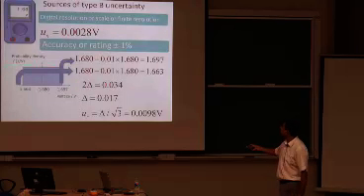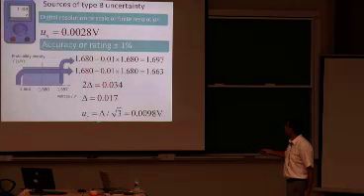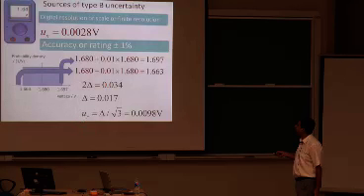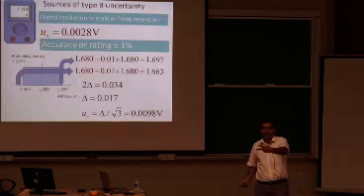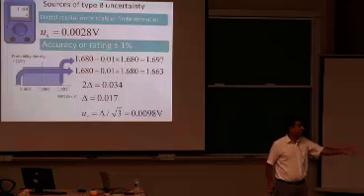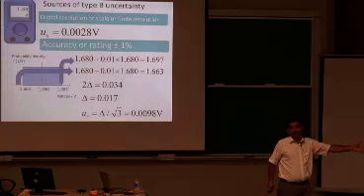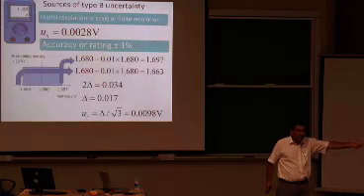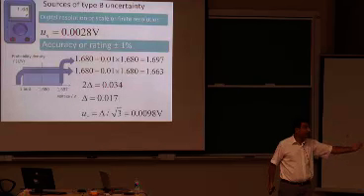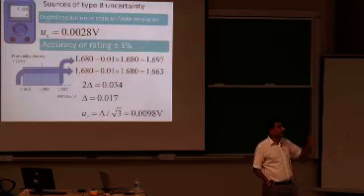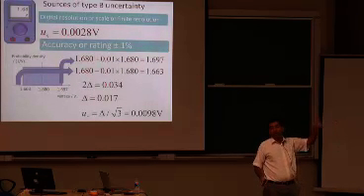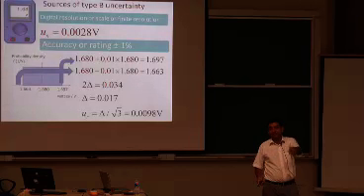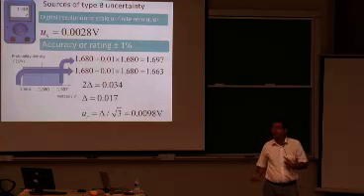So now I have 2 delta, I find out what delta is, and then I again divide by root 3 to find out the uncertainty due to rating. So I have 2 sources of uncertainty here. I have specified them. And no computer will tell you what the sources of uncertainty are. You have to use your mind. And you have to use the proper formalism to find out what the uncertainties are. And it all starts with defining a probability distribution function. And I'll explain where the root 3 comes from.